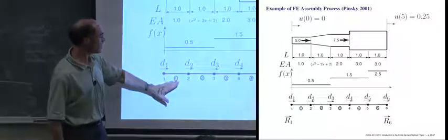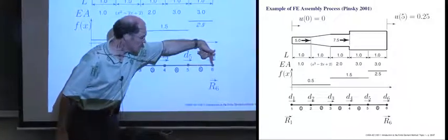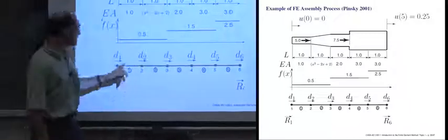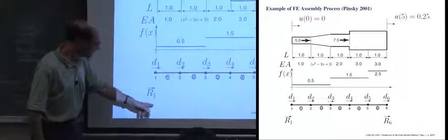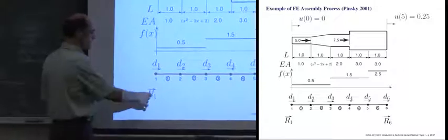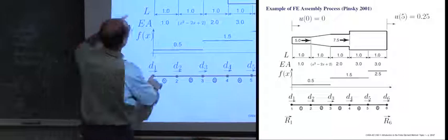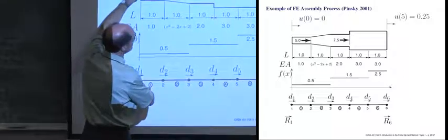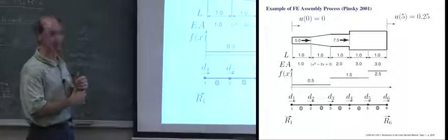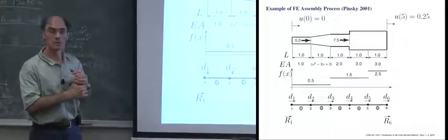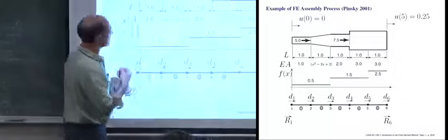And then lastly, this is our mesh. Here are our global degrees of freedom. They're potentially 6 because there are 6 nodes. There are 5 elements. You'll see here, I think for this first example, although I can show you how we can construct this, but recall that the R's, these are the reaction forces. So it turns out that wherever you have a displacement boundary condition, you will, as a result of that, have a force that you can calculate. Okay? So that is actually a post-processing step. We'll see how that works.